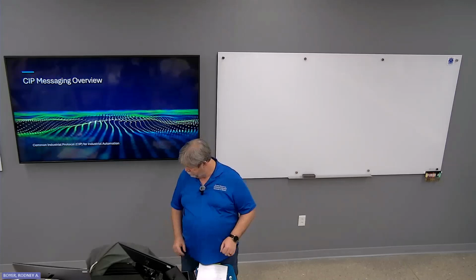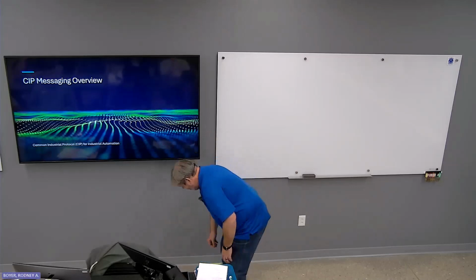Coming to find out, the VFD was interfering with the signal coming from that draw wire. So we switched over to one that was run on Ethernet, and the problem went away. Much like my clicker just did.